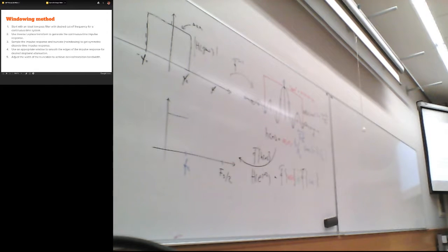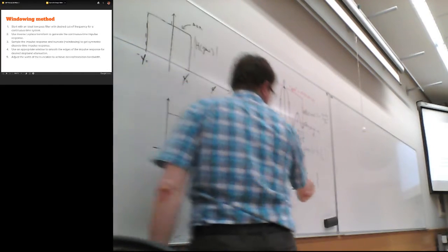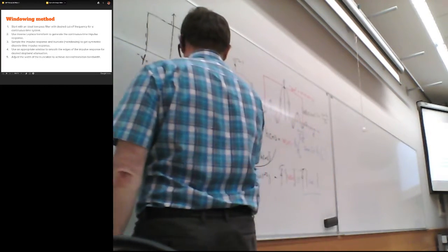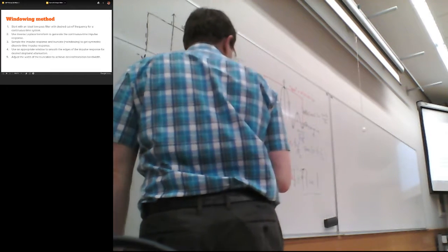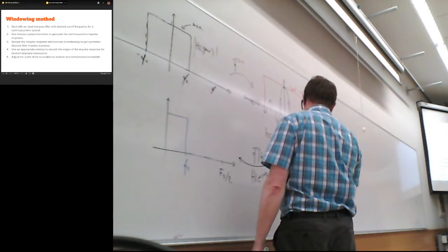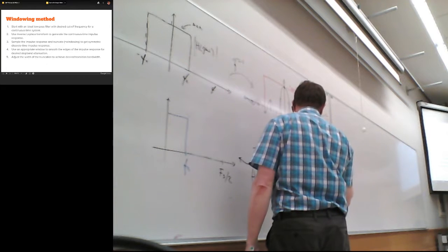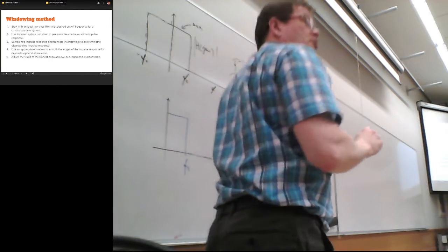But that means linear convolution. Okay, so this part here gives the box like it was in the beginning. It doesn't change anywhere. This one here, the Fourier transform of the box window would be sinc in frequency space.